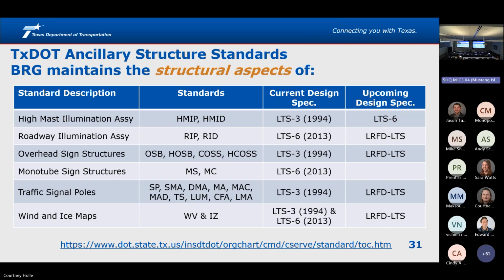We only have the 24-inch diameter, and then we're limited to the 3/4 inch pipe thickness. So we removed the ones that had a thickness over 3/4 of an inch. For us to get the spans back, we're going to have to look at increasing the diameter of the pipe. So it's going to have to be more variable than what we have right now for us to accommodate some of those longer spans.